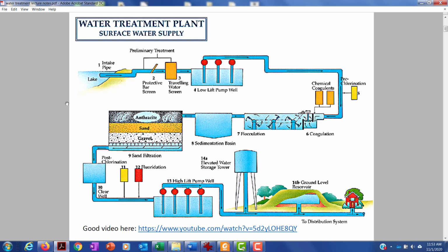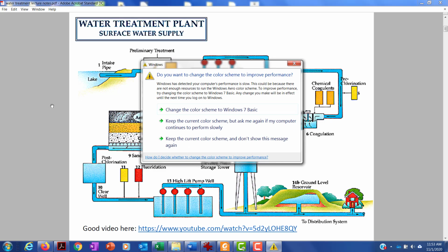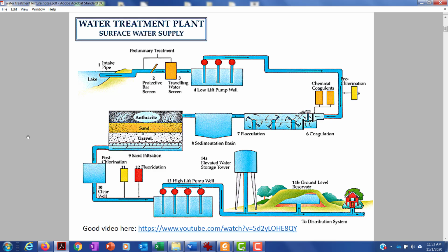And again, I think Water 4.0, the book, does a pretty good job walking you through the process of pre-treating surface water before drinking. A lot of us, because our society has made these treatment plants sort of top secret or kept them under wraps, aren't usually familiar with all that happens to their water. But if you take water out of a lake or river, it goes through a lot of pre-treatment, mostly because natural water has lots of little suspended particles, turbidity, and we don't want those in the drinking water. So there's quite a bit of actual chemical treatment of the water before it gets to the tap. You add chemicals to coagulate the little particles and settle them out, and then filter it. And then finally you boost the water with chlorine before sending it out into the system.